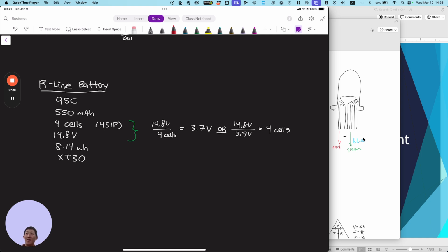And it would still have the 3.7 volts? Yes, yes. Each cell is always going to be 3.7 volts. So it's important to remember, cell sizes come in different shapes and sizes. There's no standardization when it comes to that. So the only true way to know is to open it up. You can open it up and then you can look, okay, it's one cell. There's not 2 underneath here. Okay, great. So that's how you tell.